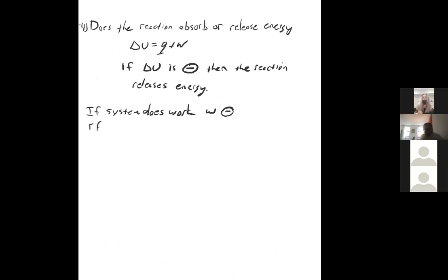If the piston does work, W is positive, okay? So let's put it together. Q was positive 139 kilojoules. And now W, since in this problem the work was done by the system, the work is negative 155 kilojoules. Okay, so we've got a number there.